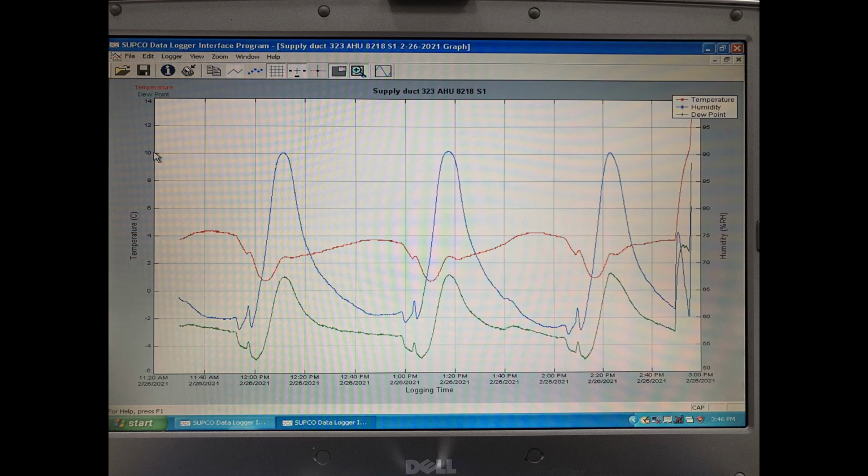And these are the measurements I did, and as you will see here, the relative humidity goes up to 90 and then goes down to 50, while the temperature goes up to 4 and then goes down to 1, which is not good news because it's February and outside it's about 5 degrees Celsius. So when the summer comes, it will be a serious problem.